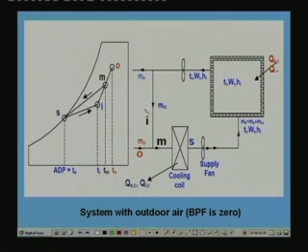Okay. So, this one air stream and this second air stream, these two air streams are getting mixed. This air stream is coming from the conditioned space at the same condition as that of the space, and this air stream is coming from outdoor. That means both are getting mixed, and we would like to find out what should be this point. So, that is obtained by again applying mass and energy balance across this point.